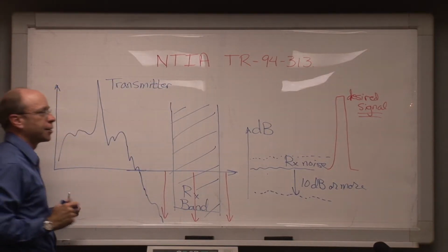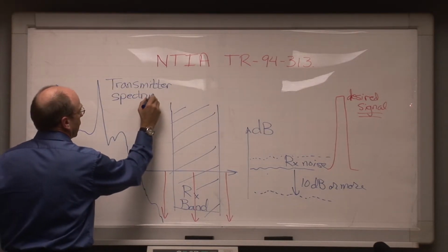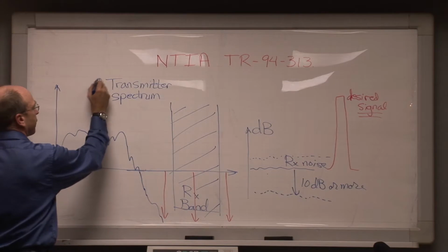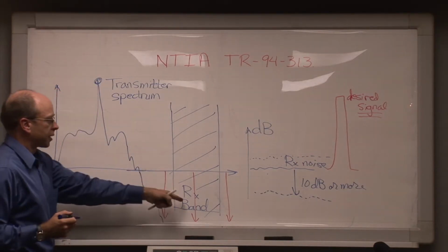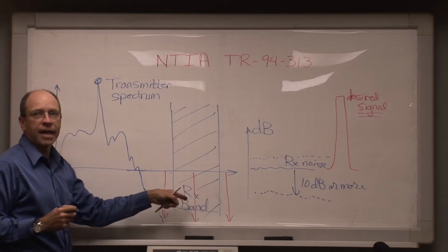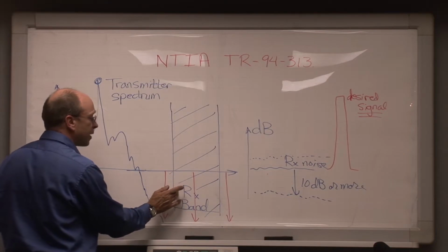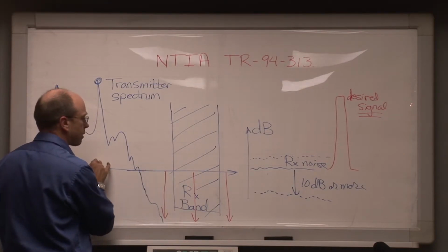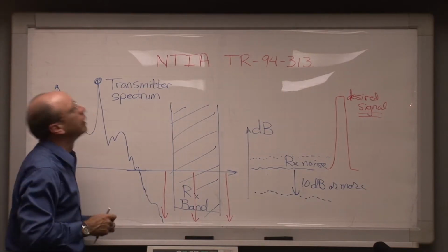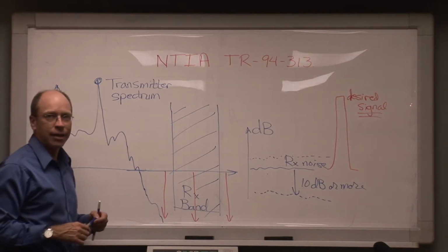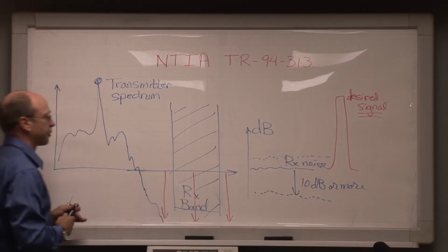barring case penetration, the only realistic way for this interference to be occurring is if in fact this thing is generating the front-end overload problem. And again, another clue is that this receiver presumably has no filter or has inadequate filtering at its front end. If this receiver does have adequate filtering at the front end and you're still seeing the front-end overload problem, now you've got a really exotic situation, which we did deal with and which I'll talk about in the next talk in this series. But we'll assume, first of all, that this is going to be a simple case, not a tricky case.